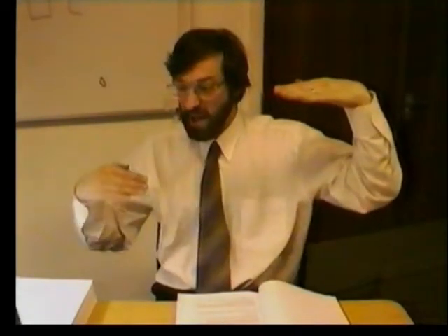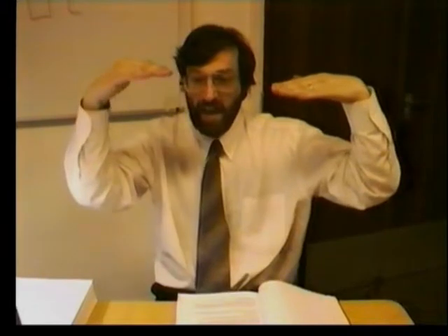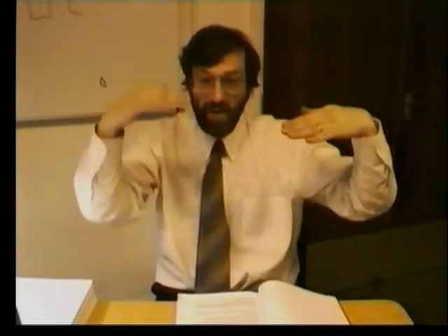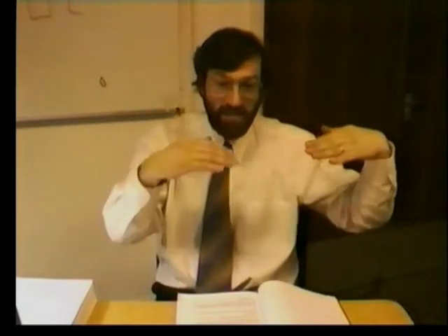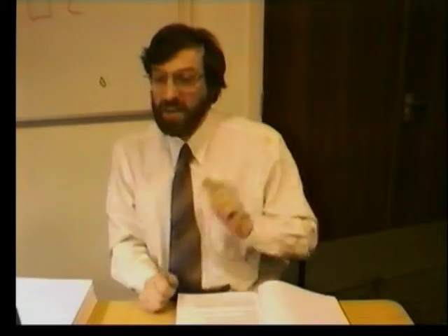So what happens is, here's our unknown voltage, and our counter will be down here. And go until it finally matches. And then, as the unknown moves up and down, our counter will track it and follow it, tracking and holding, using this up-down technique. Now, you might think that's incredibly fast. In fact, once it's locked on, it is actually extremely fast.